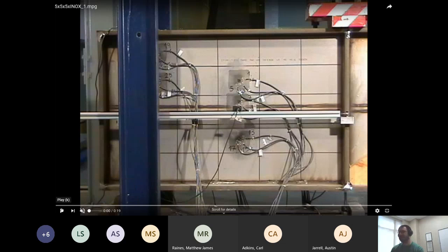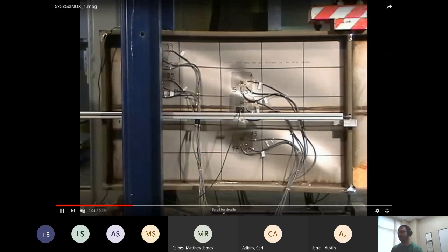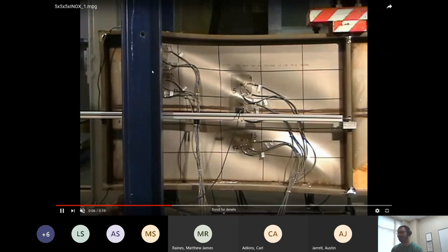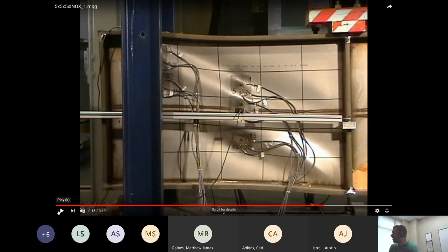And so when you load this thing in shear, you can see it's going like they've time-lapsed it. And you can see what's happening is it's kind of folding along the center. Does everybody see that? So that's a shear failure. It's also kind of funny how that thing's failing, and it looks like it's at a 45-degree angle, kind of like how concrete beams crack at a 45-degree angle because of Mohr's circle. Well, the same thing's going on here.